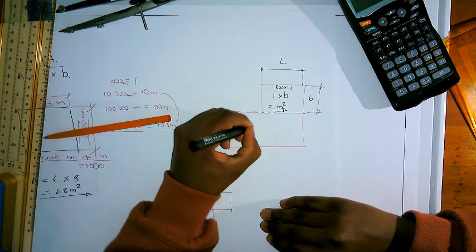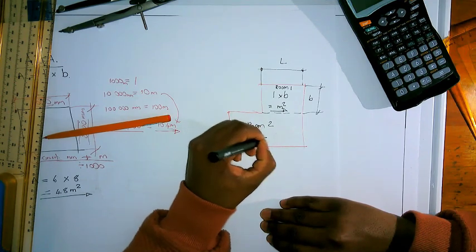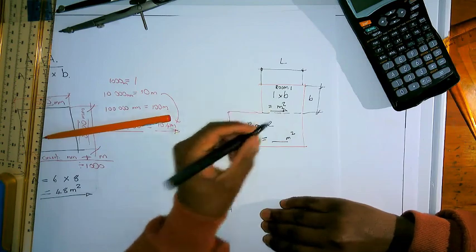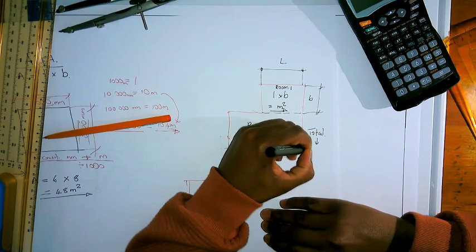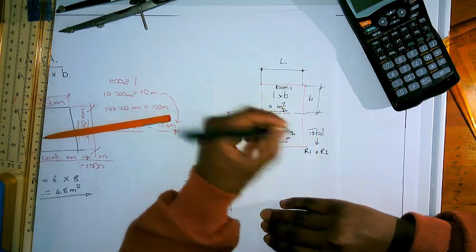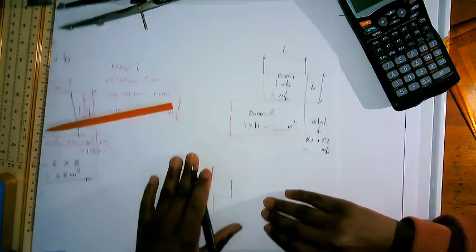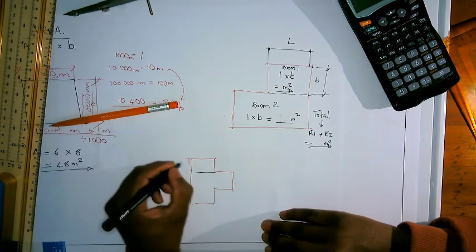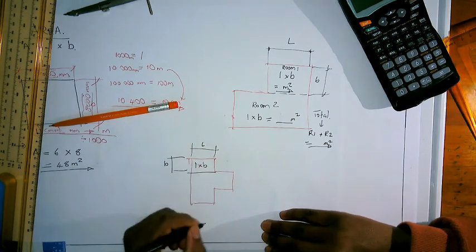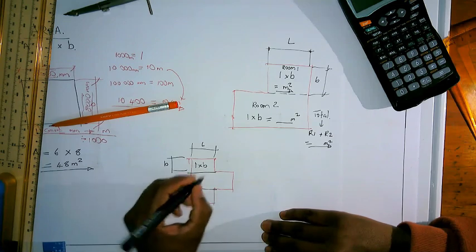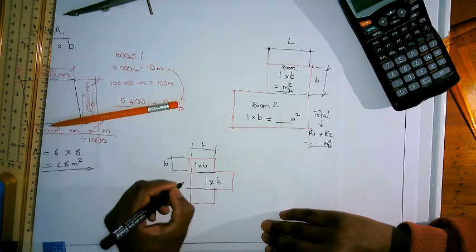Look at how I'm going to do it for the third image as well. I've got a unique shape here for my building. What I'm going to begin to do first of all is divide it into 3 equal parts. Then take note of each side with length times breadth. So divide each block, then multiply the length times breadth together of those measurements, and then add them to get a total. And don't forget, your answer must be in squared meters. So whatever unit of measurement you use, squared.